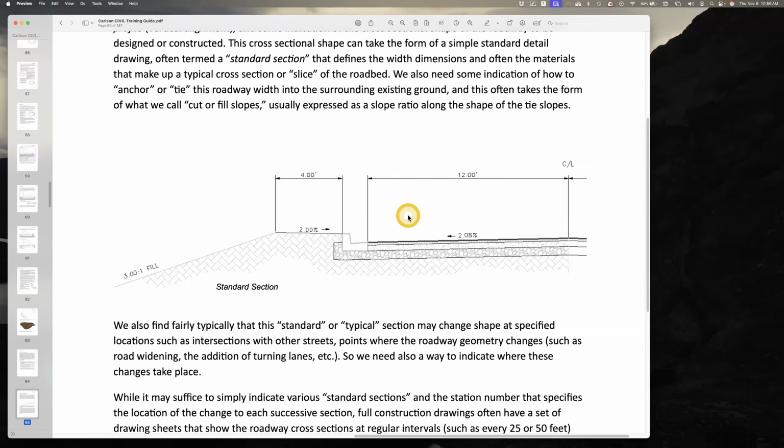And it's going to take the average of them because the assumption is that the road changes linearly, not literally, but linearly. It changes between station drops. So if I've got 10 yards of cut, let's just talk about cut and fill.